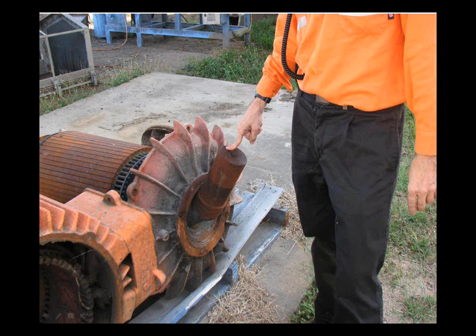Here's an example of the motor. It's a 250 kilowatt electric motor. As you can see, the shaft here was glowing red hot. This is a burn mark around the face flange of the motor. That caused the 6-inch, 150 millimetre shaft to bend at nearly 80 degrees. The fan flew off and dug into a wall. Not just the cost of the repairs, but also the safety issues. A simple vibration device or a simple temperature measurement would have avoided this situation.